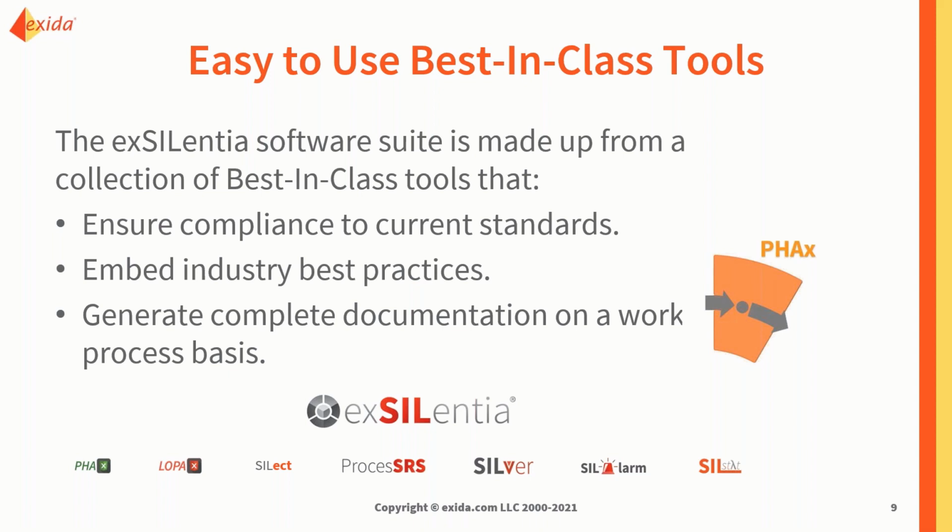And we are, I think, actually the only existing tool out there that integrates an industrial database of failure rates for different makes and models, and can then calculate the whole PFD average or PFH based on those input data, and then use Markov modeling to do a very accurate mathematical deduction based on that. That gave this tool a very good start.